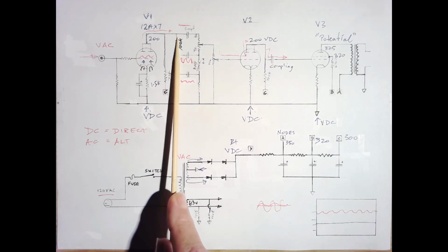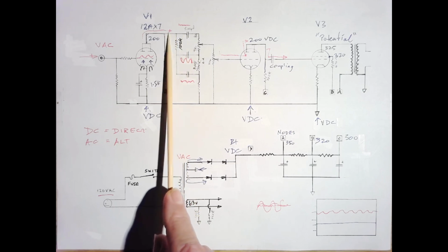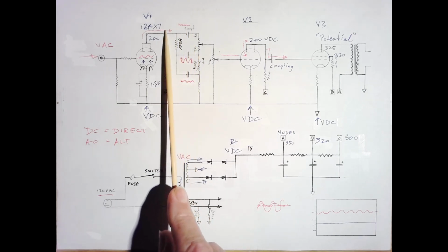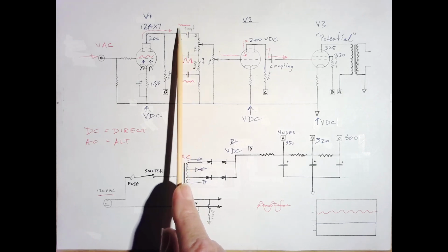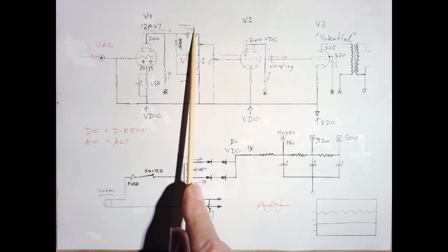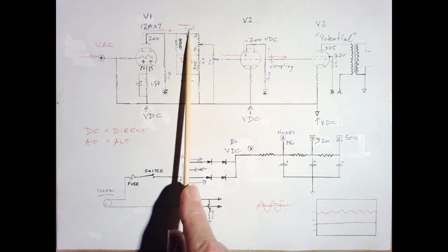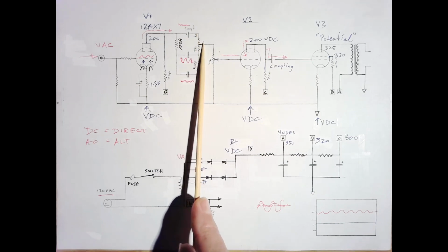the signal is more likely to want to simply pass through this capacitor here. So anyway, only the treble can get through this capacitor because it's a very, very small value, and 500 picofarads or 250 picofarads only allows very high frequencies to pass, and they are then controlled by the treble.